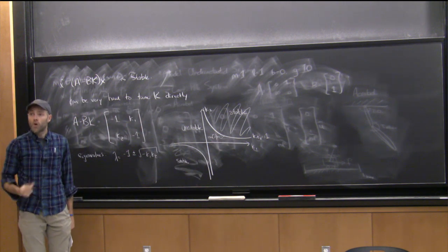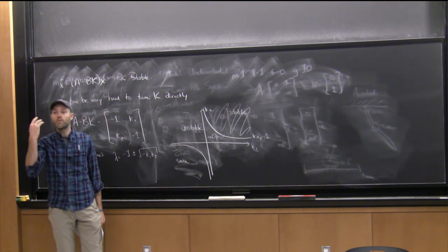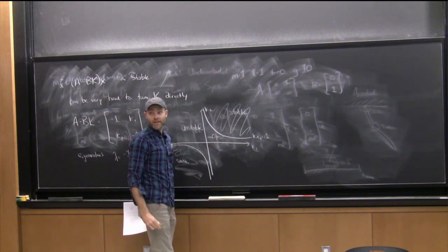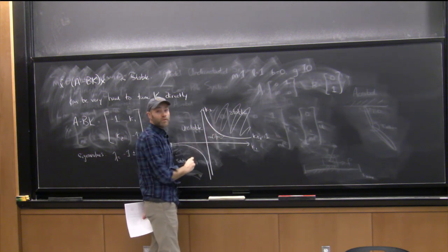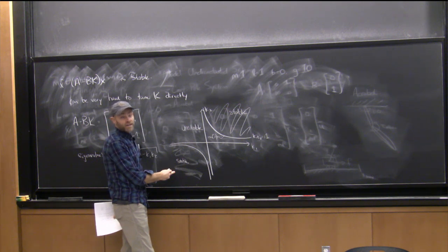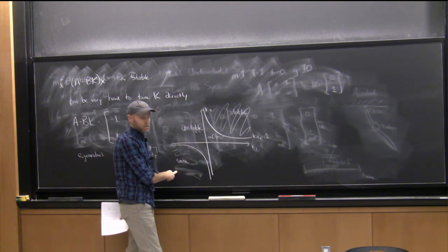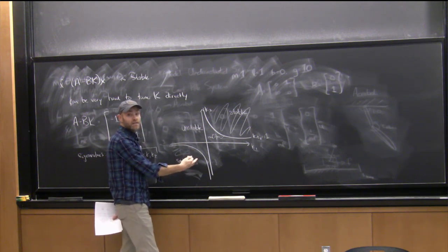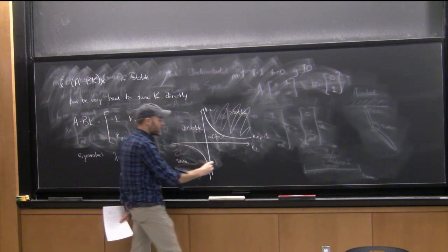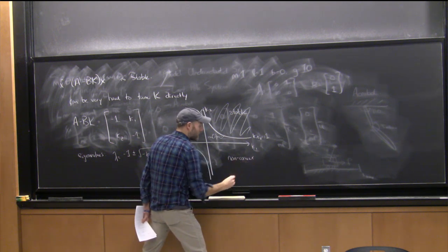Okay? So if your goal is to maximize some criteria of performance, and your strategy is to start guessing a K, and then move around and try to improve it, the best thing might be way over here, and you're going to have a hard time just kind of changing K a little bit and finding that solution. Right? So in general, even for linear feedback, the stabilizing controllers, this is an example, are certainly non-convex sets and even disconnected sets.